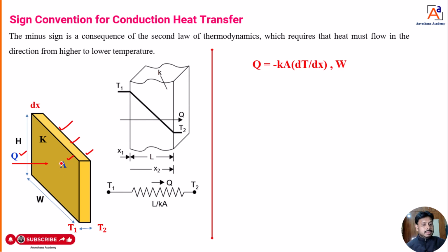That metal plate has an area represented as A and thermal conductivity K, the thickness of the metal plate is dx, the width of the plate is W and the height of the plate is H. So the heat is going to transfer across the thickness of the metal plate. At the high temperature face I will mark the temperature as T1, then at the low temperature face I will mark T2, dear students. To better understand, I will take this thickness and assume it as a front view.